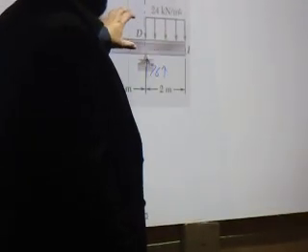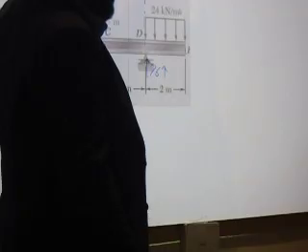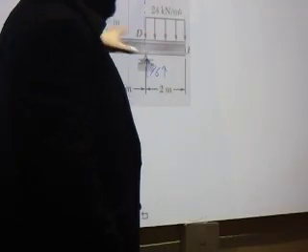The 76 goes up. 76 minus 28 will be what? 48. Then it will gradually reach 0 here because that's a typical cantilever, but the shear must be 0. Okay? This is my shear force diagram. And again, as mentioned yesterday, you will notice that the concentrated moment doesn't show up anywhere in the shear force diagram. It's not there at all. Okay? But let's now do the bending moment diagram.